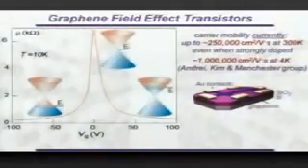So the consequence of this extremely fast propagation of those electrons is that if you make a transistor out of this material, and it's quite easy to make a transistor out of this material, it would work extremely fast and at very high frequencies. The figure of merit there is called the mobility, how much scattering your electron experiences as it moves.